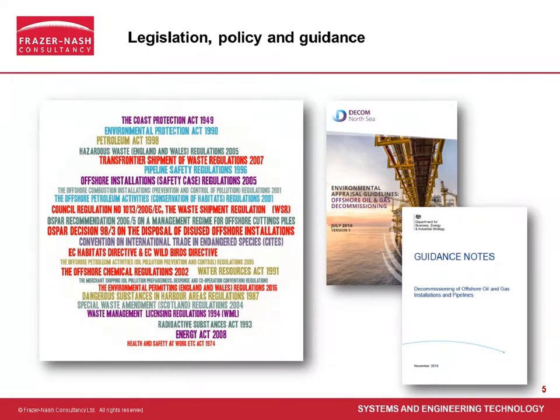There may be requirements for marine licences under the Marine and Coastal Access Act or the Food and Environmental Protection Act for deposits in the sea. There may be a requirement for chemical permits for the use or discharge of offshore chemicals. These would be under the Offshore Chemicals Regulations. Under the Offshore Petroleum Activities Oil Pollution Prevention and Control Regulations, there may be a need for oil discharge permits. There may be a need for marine survey consents, such as marine geological survey consents under Offshore Petroleum Activities Conservation of Habitats Regulations.